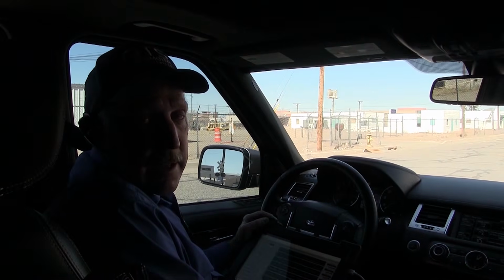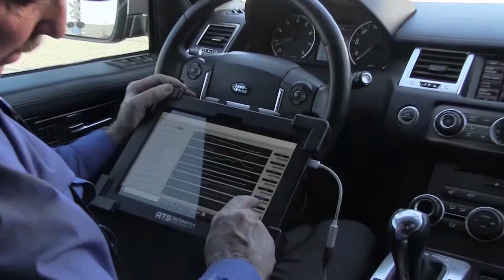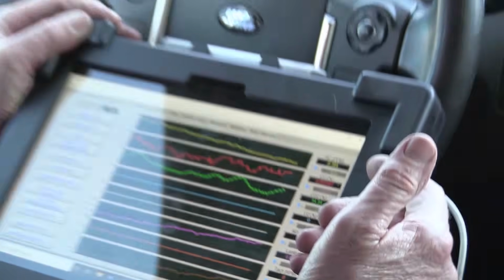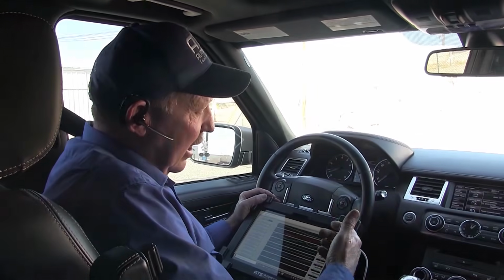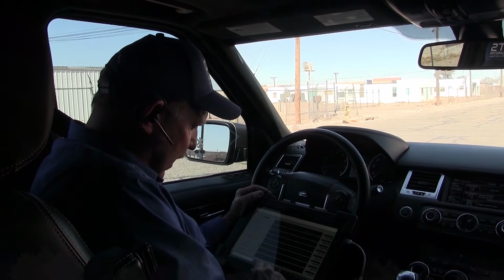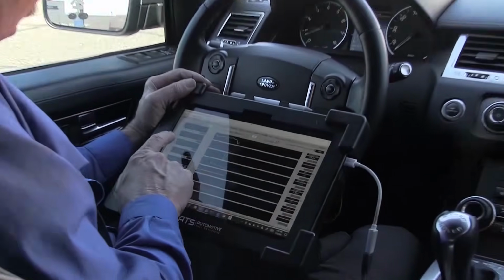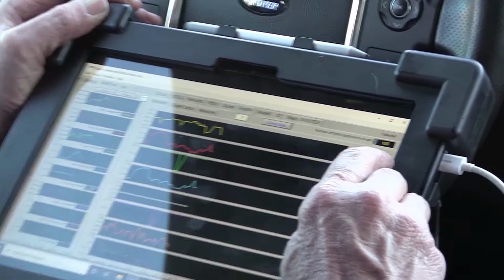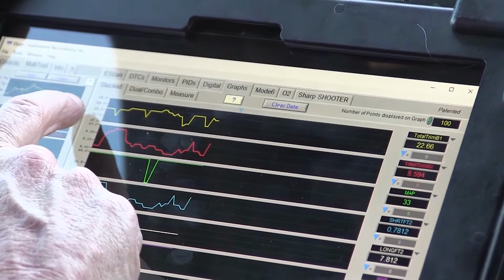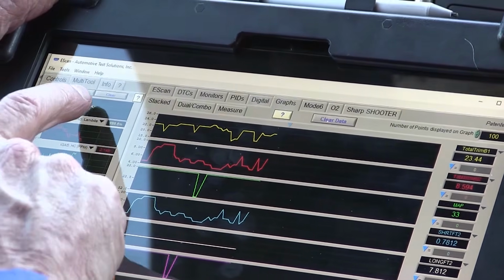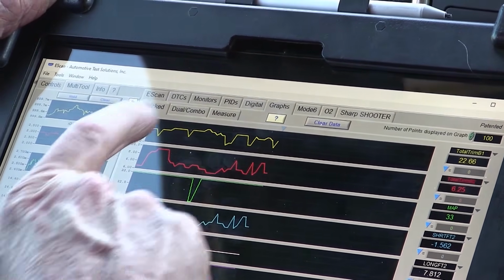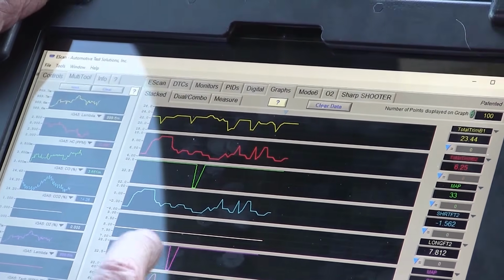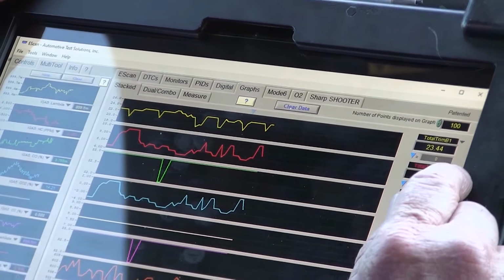We have the 5-gas data up, so let's take a look at it. We've got 0.999, that's a lambda of 1. So that's stoichiometry. That means that we're controlling the fuel right now. So I want to go back over here, and we can see my total trim is 23%, and I can see I have a lambda of 1. I'm graphing the gas analyzer's gases on the same screen as we have scan data. So this is really handy for a problem like this.